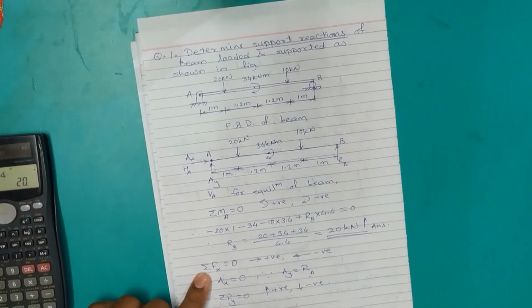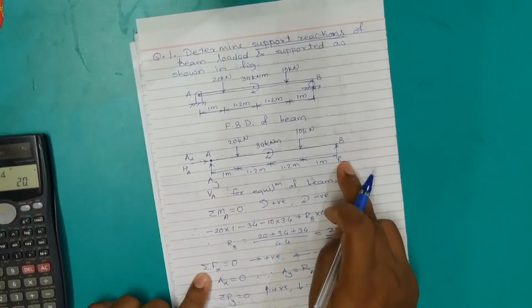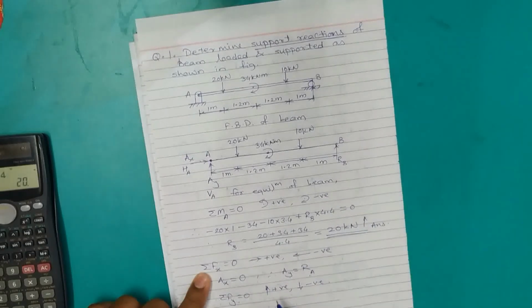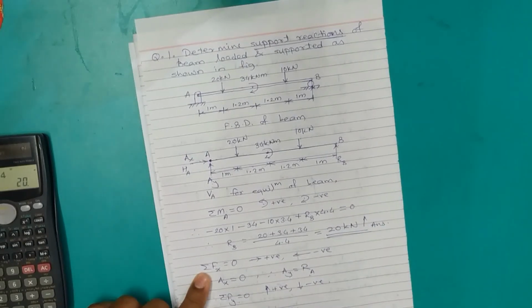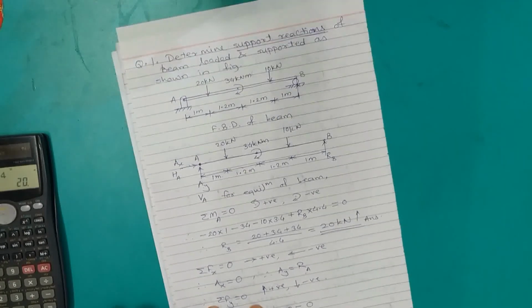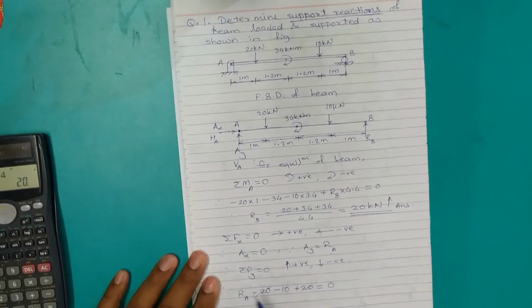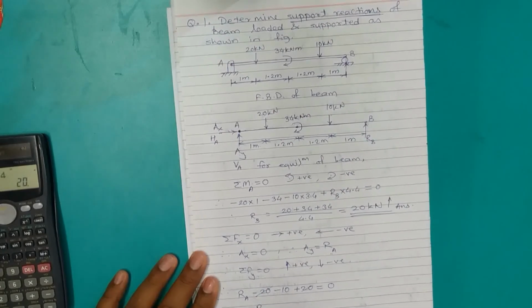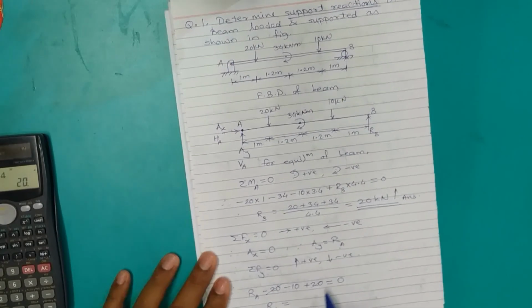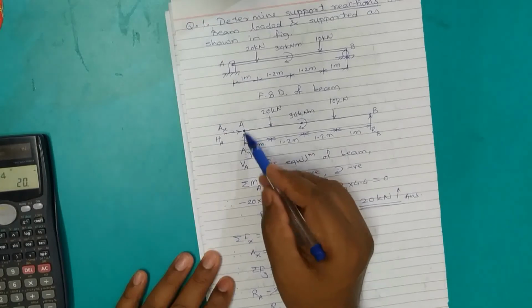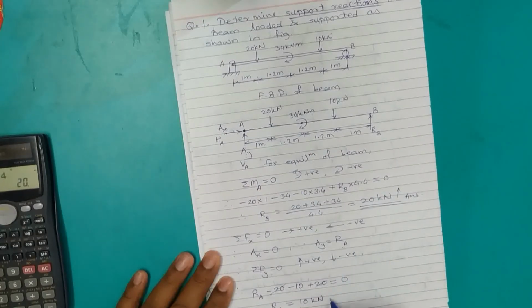Then minus 10 kilonewton, which is also going in the downward direction, and RB that we have calculated, which was 20 kilonewton in the upward direction. So let's take it plus 20, and that total summation Fy has to equal 0 because of the equilibrium. So simply here we are getting our RA component, the resultant of the hinge, equal to 10 kilonewton, and because it is positive, whatever direction of AY or RA we have taken is correct. So these are the answers.